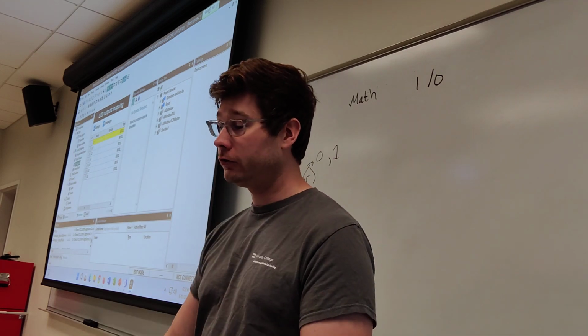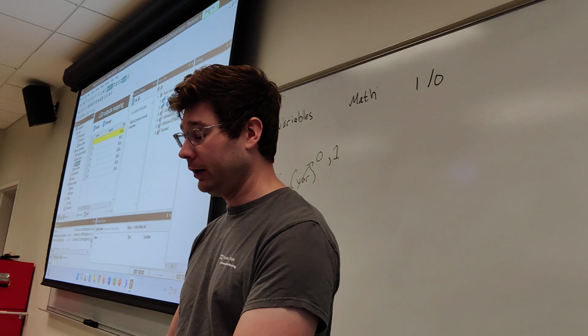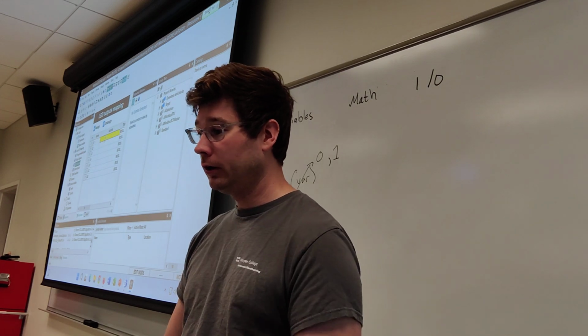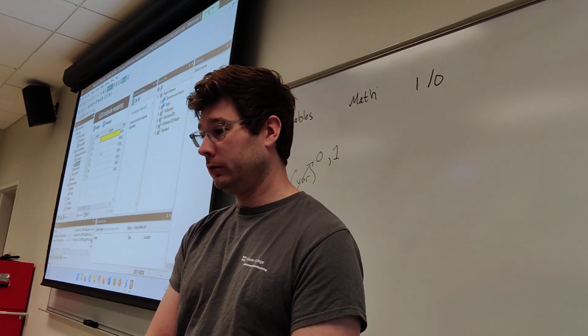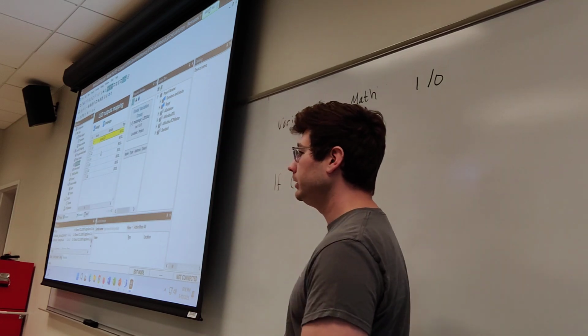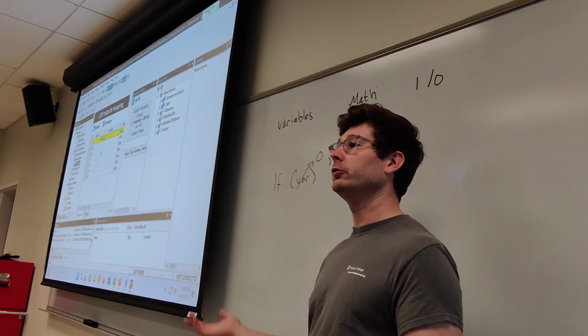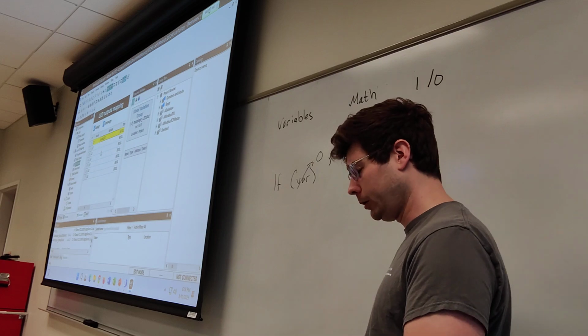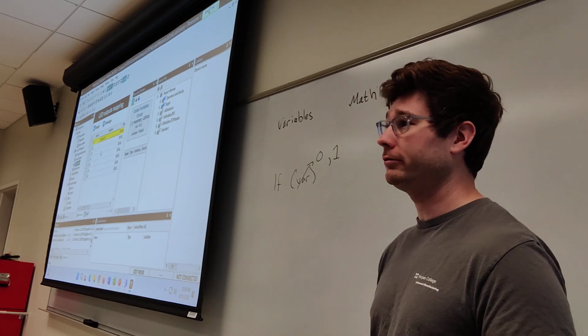So for example, if my relay 1 was a motor, I might call light 1 motor LED. And now whenever I set motor LED equals 1, that LED will turn on. Motor LED equals 0, it will turn off.